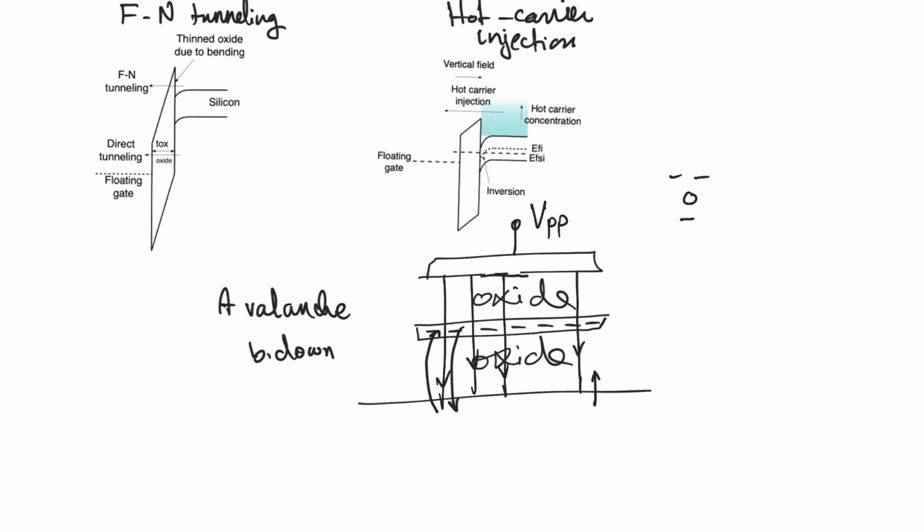They release more electrons than the electron that hit them. And these electrons themselves are very energetic in the field. They hit more atoms and release more electrons. And so you get a chain reaction similar to a nuclear reactor, and you get more and more electrons, and the oxide basically becomes a conductor temporarily, and these electrons all flow upwards against the direction of the electric field.